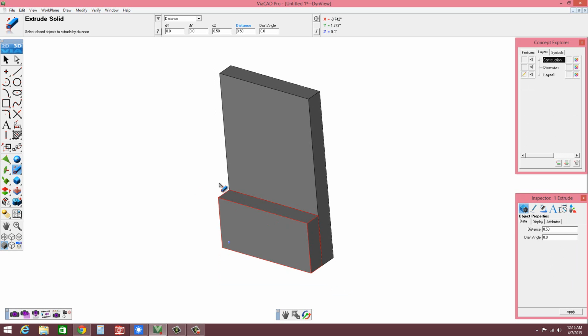Now you can see that we extruded that, but there's a little edge here. Essentially there's a sketch under there too, but these two solids need to be merged as one, or united through Boolean union. And so you'll see over here there's the add solid.